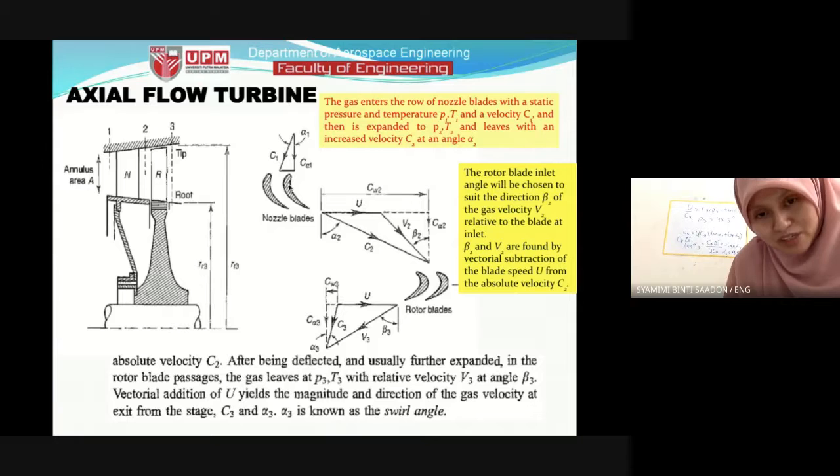Okay, so we have the nozzle. The nozzle blade is this way, kind of like this. When exiting the nozzle blades, the rotational speed stays the same for an axial turbine or axial compressor. U is the same. So we know it is in this direction, U.